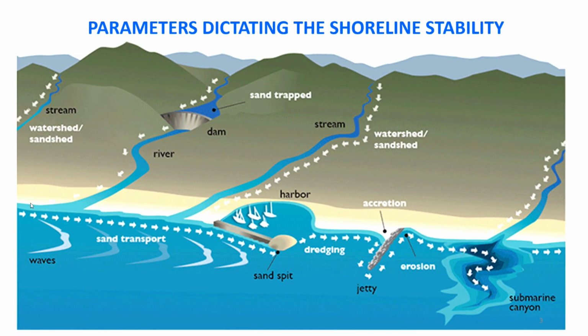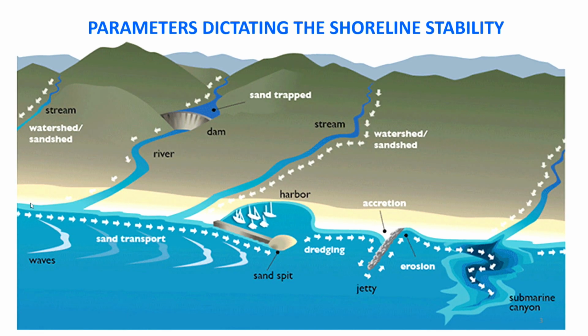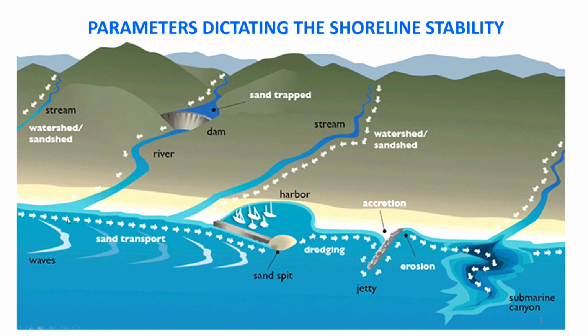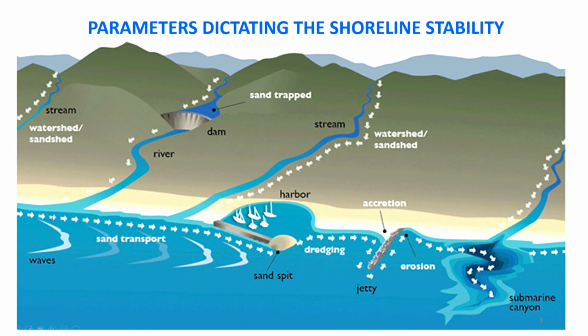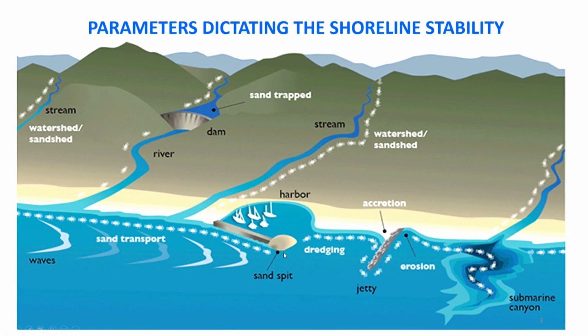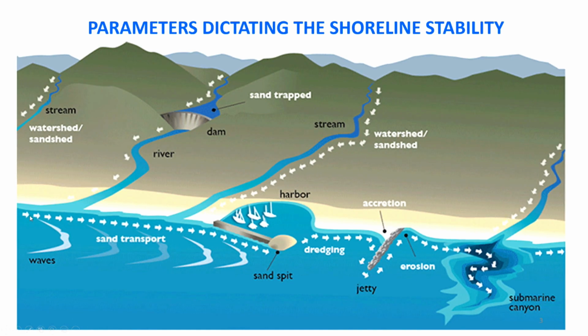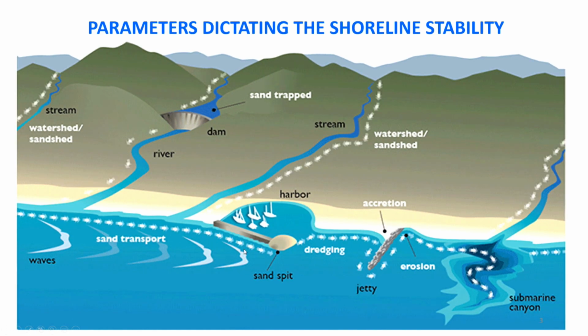A person who is visiting almost every day may not feel the movement of the sand during a non-monsoon period, under normal circumstances. What is actually happening is, when the waves are coming and hitting the coast, there is a flow taking place along the shore, and these are called longshore currents. So they are going to pick up the sand along the beach and transport it.